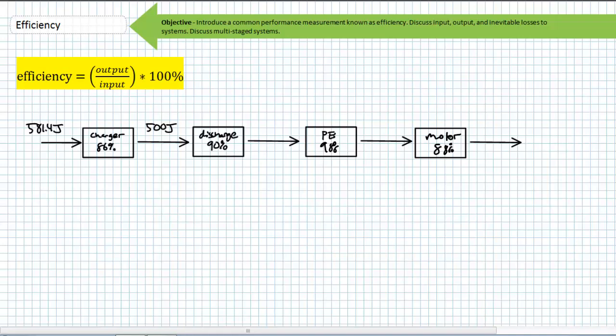If you ever played the game telephone before, you realize your output will suffer cumulative losses with increasing number of stages, and the efficiency rating for the complete system can never be greater than the least efficient stage. If it helps you understand cascaded efficiencies, use the visualization that each subsystem represents a window that is progressively narrower as you go from one level to the next. At each point, a portion of that stage's input is shaved off and lost to the following stages. What you'll find is that though each stage may be individually efficient, the whole system's efficiency is substantially less efficient than the least efficient stage.